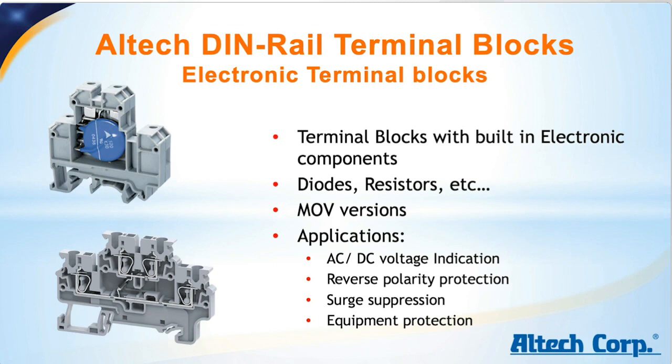It can be, for example, an MOV, to give the MOV an easy connection point to wire it instead of soldering. So you can see one here in the top picture where the MOV is soldered into the terminal block, and then the legs of the MOV can be accessed through a double level terminal block.